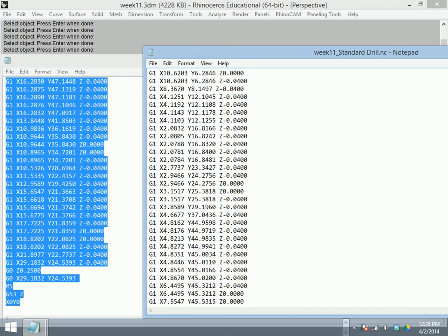Double check everything. Make sure our Z heights are right. We'll see a lot of what's happening pathwise, and we'll look at what our Z is. Z is always the critical, because if we go too far in the X or in the Y, there's stops that will stop the machine before the thing explodes. And then we'll run it. Okay, and it'll take about 5 minutes to cut. It won't take long for us to cut. It's going to get more complicated once we start doing complex patterns on the surface, especially on full depth cuts.